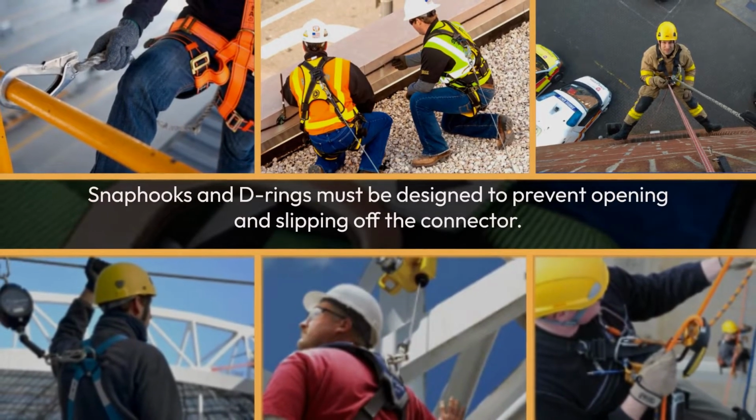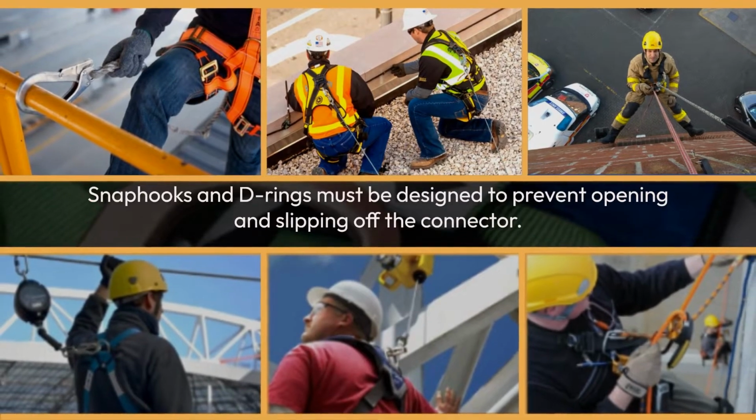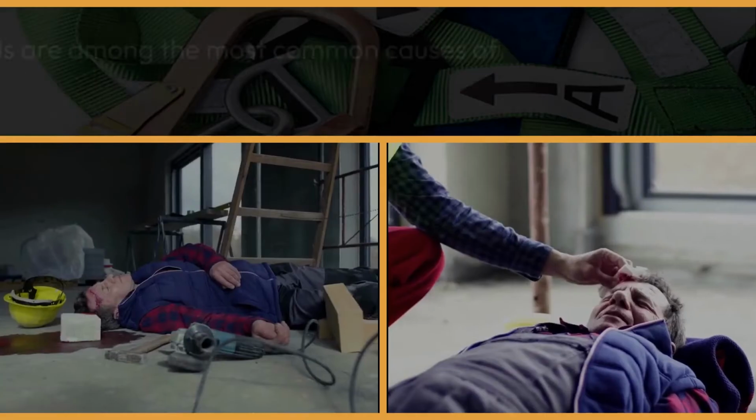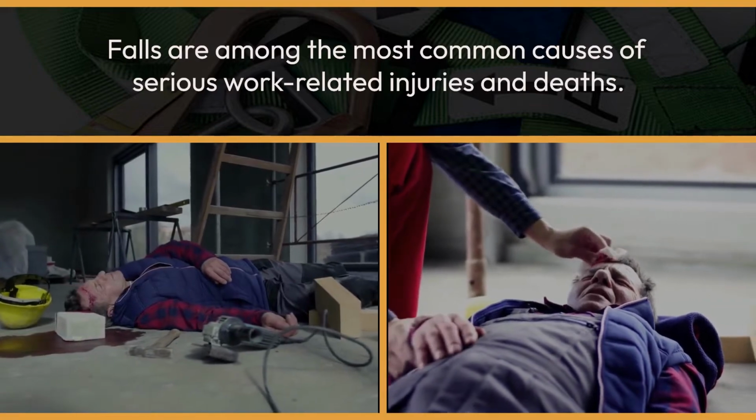Snap hooks and D-rings must be designed to prevent opening and slipping off the connector. Snap hooks and D-rings cannot directly connect to webbing, rope, wire, or any object that could cause a snap hook to open. Falls are among the most common causes of serious work-related injuries and deaths.